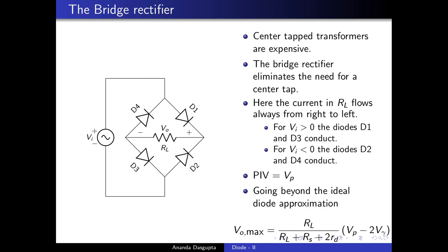So this is again full wave rectification, and the full wave rectifier using a bridge rectifier has some advantages over the standard full wave circuit which uses a center tap transformer. But all of these circuits, the half wave rectifier, the full wave rectifier, all of these have one basic problem. The problem is they essentially show a large amount of ripple.